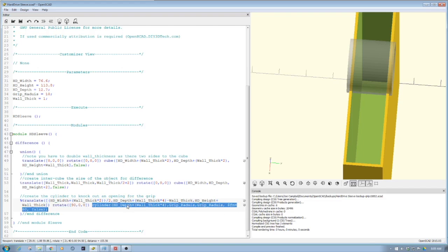However, notice that for the wall thickness, we had to add it back in. Now I went times 4 to make it stand proud. So you notice that it always stands proud the width times 2 of the box. So I get the extra width out here, so I clearly am proud of both sides of the box, and it'll make a nice clean hole both in image and production. And it's parametric too, so no matter how you scale the box, it'll always be that much more. So just a little workflow tip.